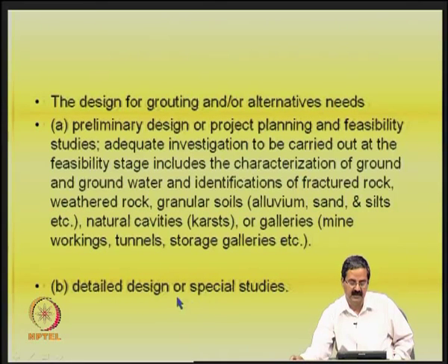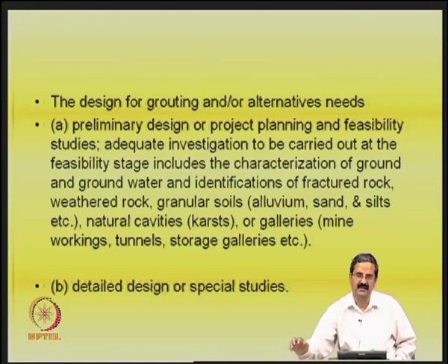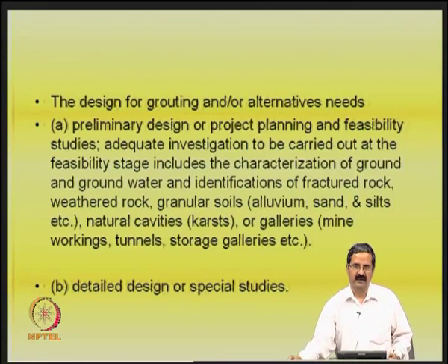So, the design has to be more careful, because you need to have all this basic information. Essentially the design consists of what type of material you need to choose as a grout, what should be the spacing, what should be the pressure. There are many methods of grouting that we have.